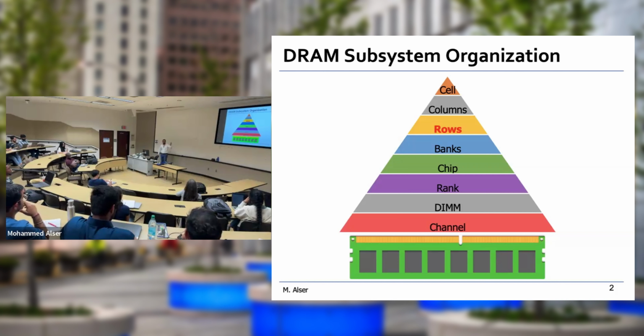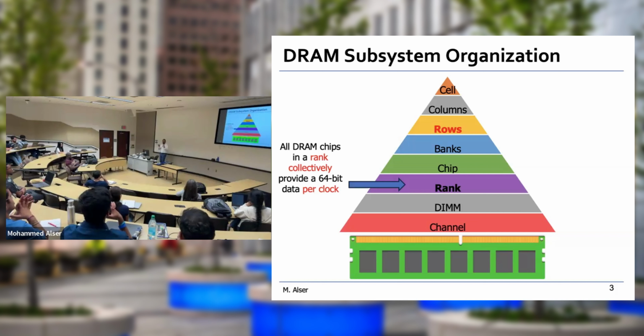So each of those chips can work at the clock edge, and whenever you get a positive edge, they give you something, right? That's why we fit multiple of those chips. At each positive edge of the clock cycle, we got something out of every single chip in the rank, and that will give you collectively 64 bits, okay?